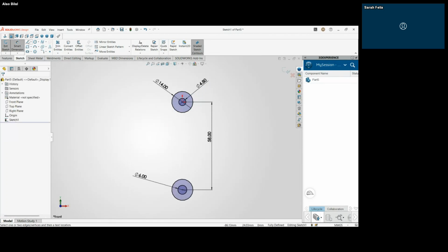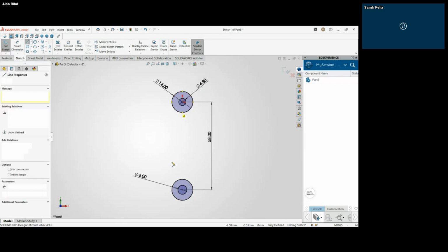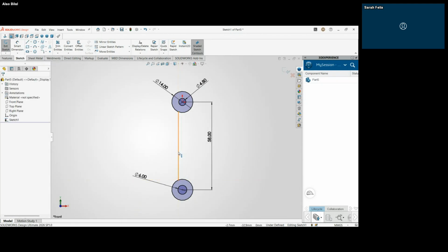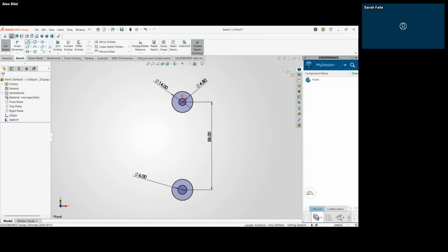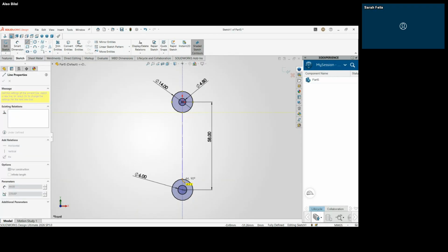So what next you are doing is to create a line from this point to this point, a horizontal line. You can actually use a center line, then you would offset it to both sides. That also works. Let's do that so that we'll be able to understand new features as we are going. So let us click on, no, we are using a center line because it's not needed. So from the center point to the center point.